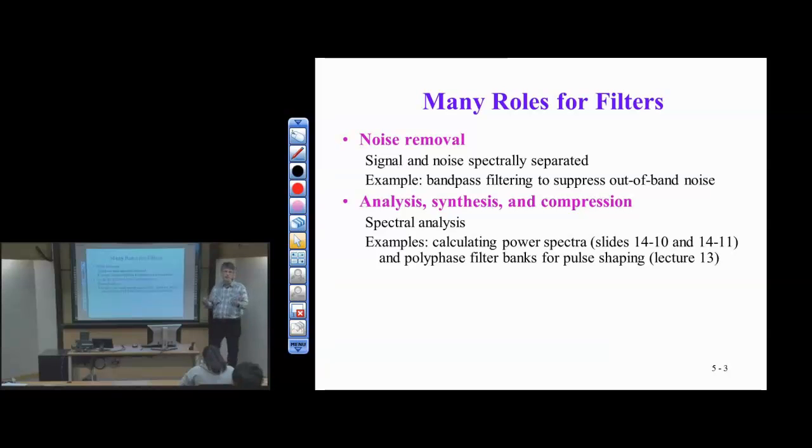The answer is yes. So this will be a low-pass filter, and then we'll follow that with up-conversion to make it a bandpass transmission. So multiplied by cosine to shift the center of the baseband to the new carrier frequency. Okay. So we'll do this both on the transmitter side and the receiver side. Anyway, I can think of this as a way to synthesize a new signal from an existing one.